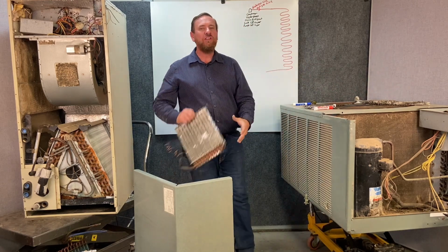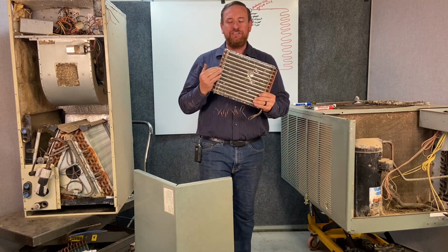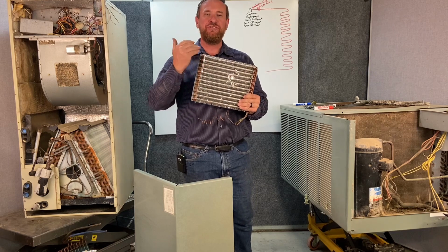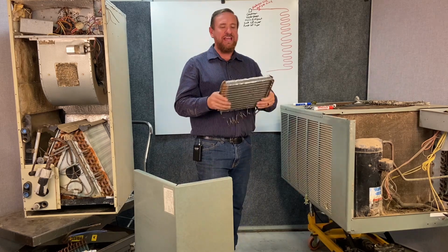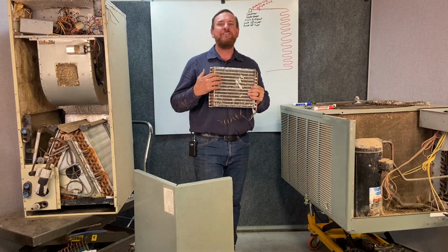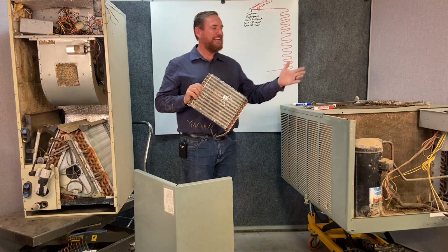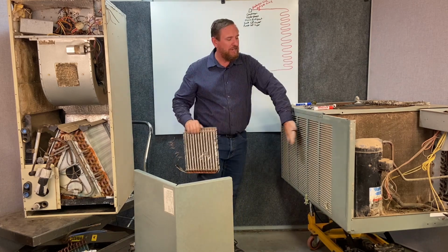So there's a whole lot of surface area. There's a lot of air touching a lot of this metal. And also the refrigerant is going to be a higher temperature than the air. So heat's going to want to move, and we also use aluminum and copper. This aluminum and copper allows us to transfer heat from the refrigerant to the cooler air. So the second law of thermodynamics comes into play right here on our condensing coil.